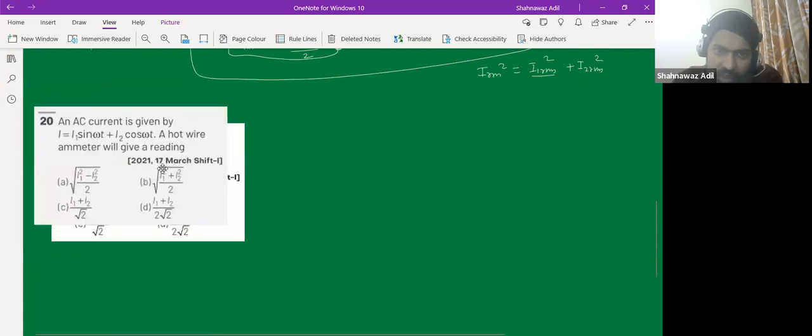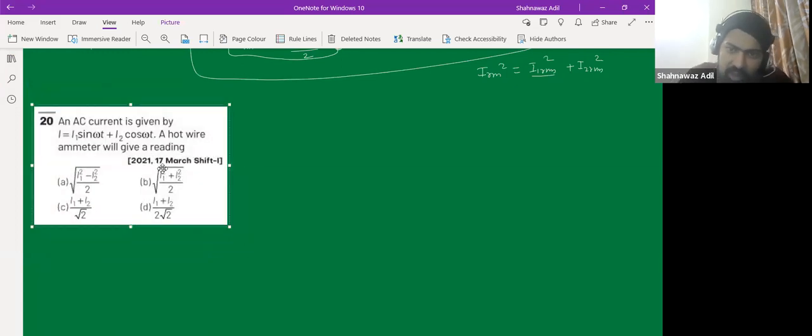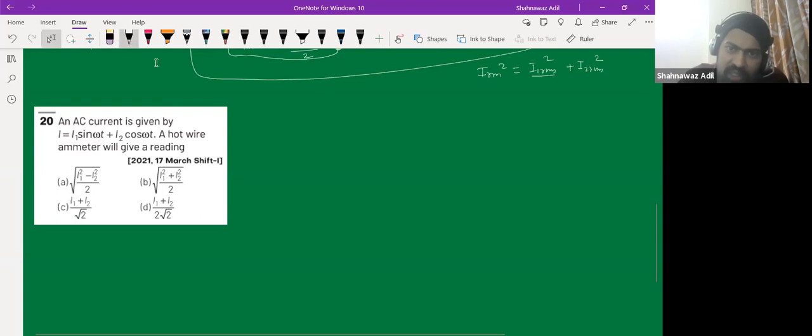So you see, you have this combination of currents, right? And you already know that the overall measurement, we measure the RMS value, right? An ammeter or whatever galvanometer measures the RMS value. So what would be the measurement that we would be getting in the ammeter? That would be IRMS, right? And this would be how much?